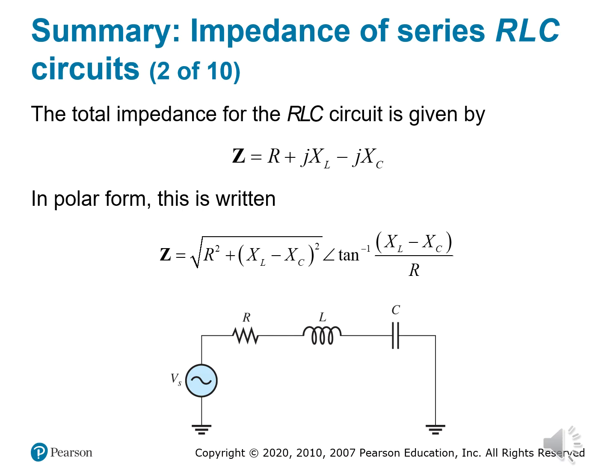And for the angle, it's the inverse tangent of the reactances over resistance. So it will be X of L minus X of C on the top divided by R. Again, doing the inverse tangent of that will give us the angle. The magnitude of Z comes from good old Pythagoras, and the angle tells us again how far out of phase the current is with voltage.